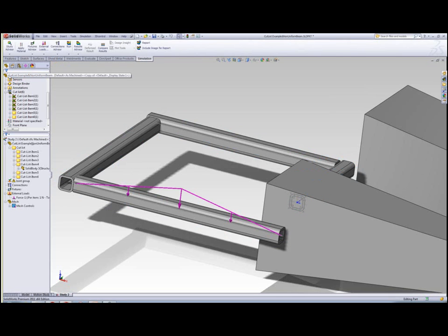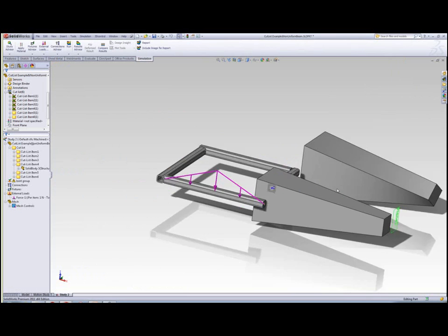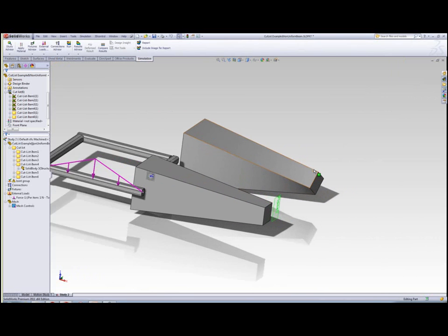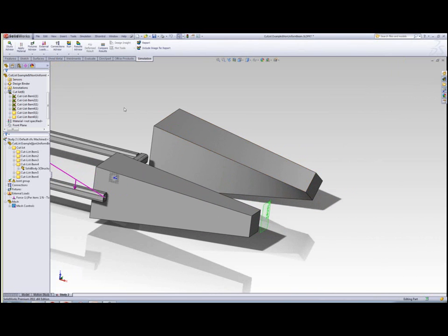Let's go in and let's talk about tapered beams. Yes, we can now do tapered beams. We can take a geometry such as these two little squared cone shapes. They're lofts, and I guess what qualifies this as a tapered beam is that it's going to be a nice uniform, equal profiled shape that runs along the same axis.